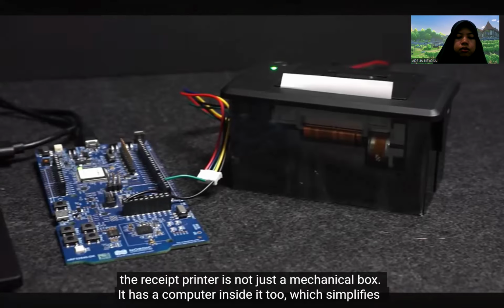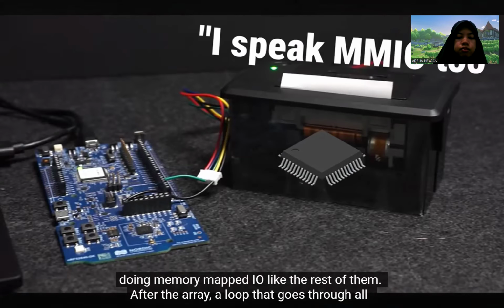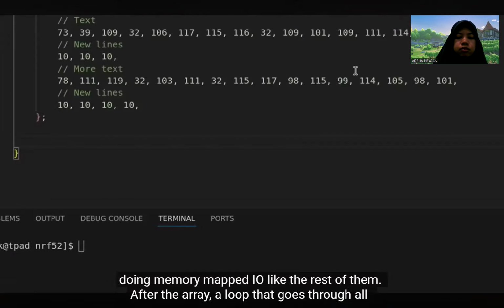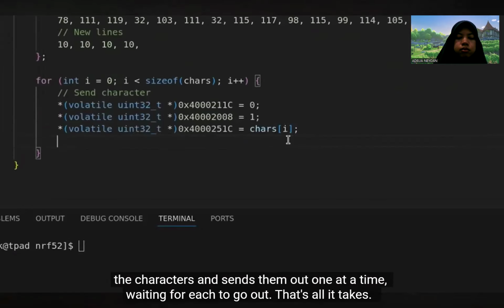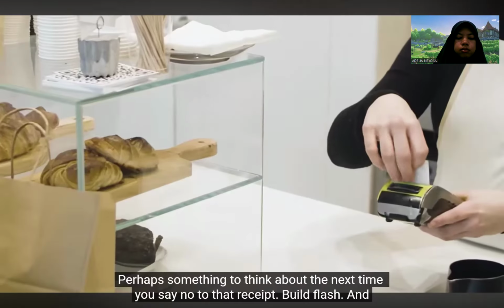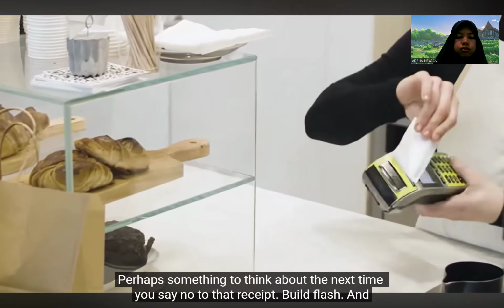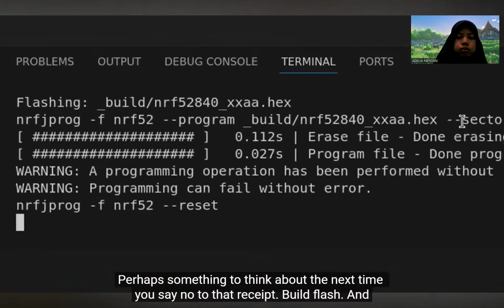To be fair, the receipt printer is not just a mechanical box, it has a computer inside it too, which simplifies the code on our end. But if we crack it open, I would bet it's just another microcontroller doing memory mapped I/O like the rest of them. After the array, a loop then goes through all the characters and sends them out one at a time, waiting for each to go out. That's all it takes. Perhaps something to think about the next time we say no to that receipt. Build, flash, and go.